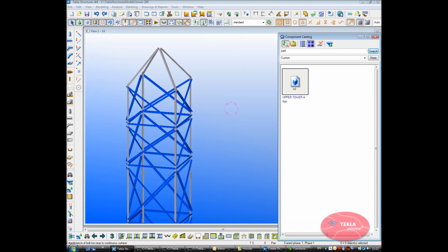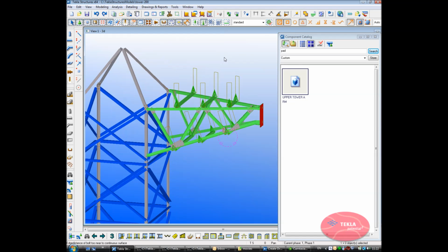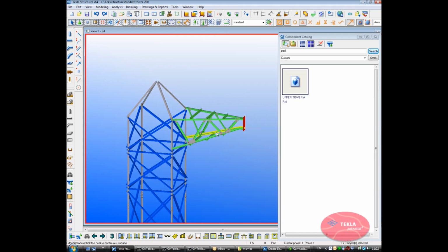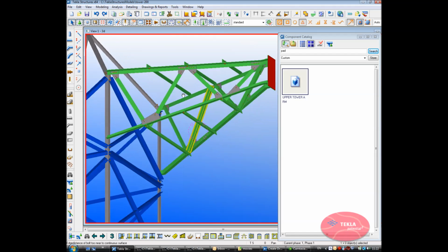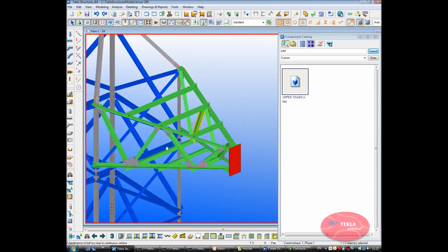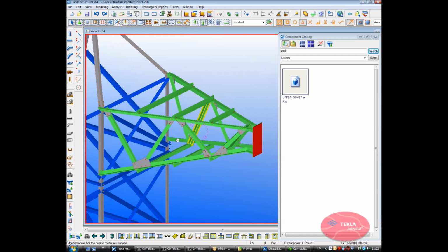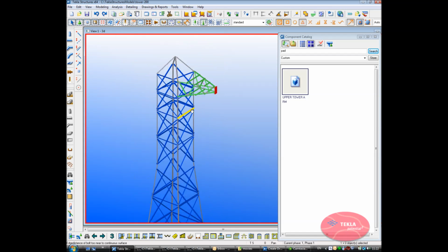Any standard reusable components such as tower arms can be made within Tekla and then reused. These can be made yourself by simply placing the elements and then storing away as complete units. So for example, here's one I've got stored away, which is for a typical arm for this structure, and if we click on there you'll see that it is stored away not only with all its member sizes but also all its connections and everything as well. So simply stored away, reusable and fully parametric.